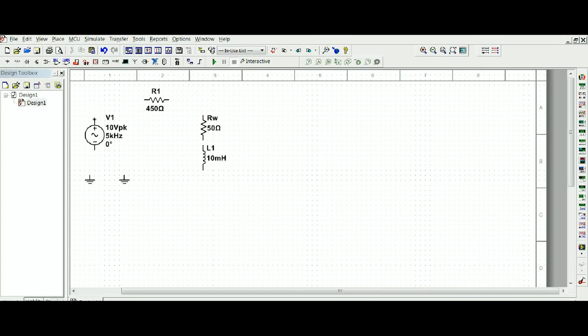So, setting my cursor on top of the signal source, I'm going to left click, drag up till it's equal, left click, set a corner, connect the resistor. Coming out of R1, go over to our winding resistance, left click, set a corner. Now with this, I could push it up and make a connection, or maybe not make a connection. It's safer to actually physically wire this. And then I'm picking up in this guy node 3, net name 3, which is not going to be useful.